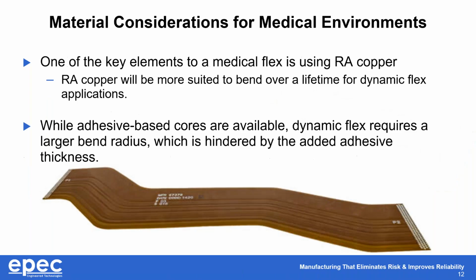Regarding the copper, one of the key elements to a medical flex, and really even just a dynamic flex in general, is using RA copper, with RA copper being more suited to bend over the lifetime of a flex, contrasting to the default ED, electrodeposited, copper.